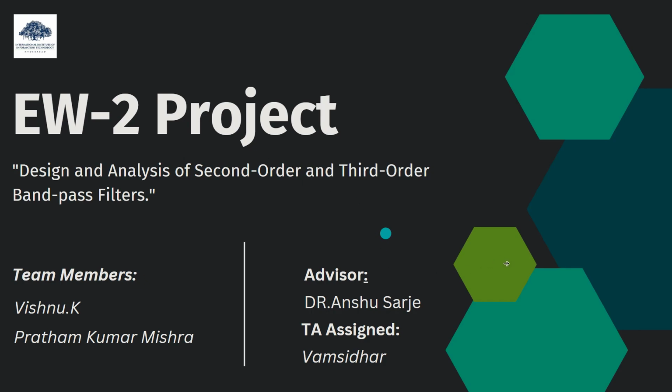So firstly, what is a band pass filter? A band pass filter is a filter which allows a particular range of frequencies, from a low limit to a high limit, to pass through it, and other frequencies are usually diminished or cancelled out. For our project we had to design a band pass filter with a lower limit of 0.5 Hz and an upper limit of 100 Hz. This limit was decided considering the limits of the ECG signal, since our project was to be made for biomedical signals.